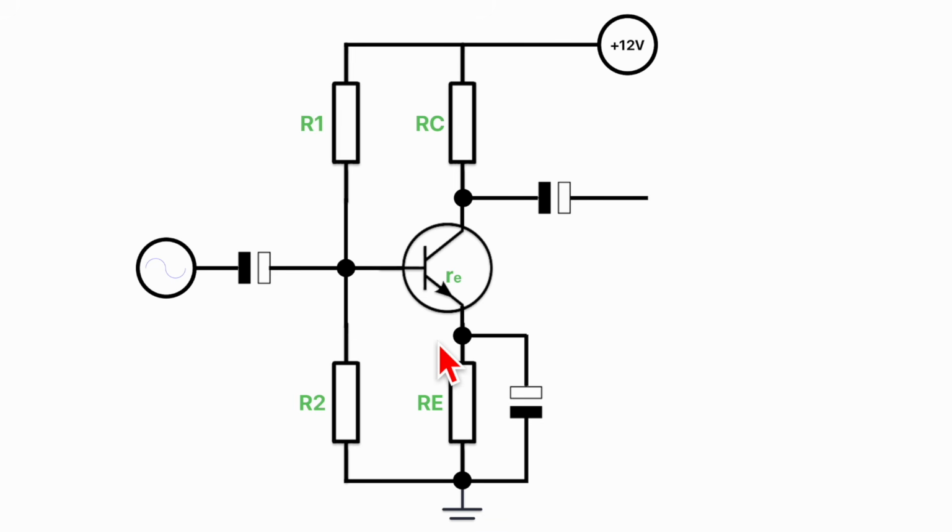That's what DC biasing is for. The reason we do it is because we want to establish what we call the quiescent operating conditions. That just means what it looks like when you've just got DC current going through it and no AC signal, because we need to get it working right from a DC point of view before we start worrying about adding our signal to it.